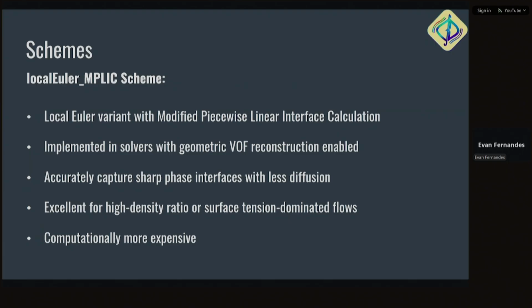So you need to have a high-end system to run this, because even on my system, to run this simple case, it took around half a day to just run one-fourth of the whole simulation. So you can expect it to run for at least 2 days on a typical 8-core system. So you can keep that in mind when you're running.